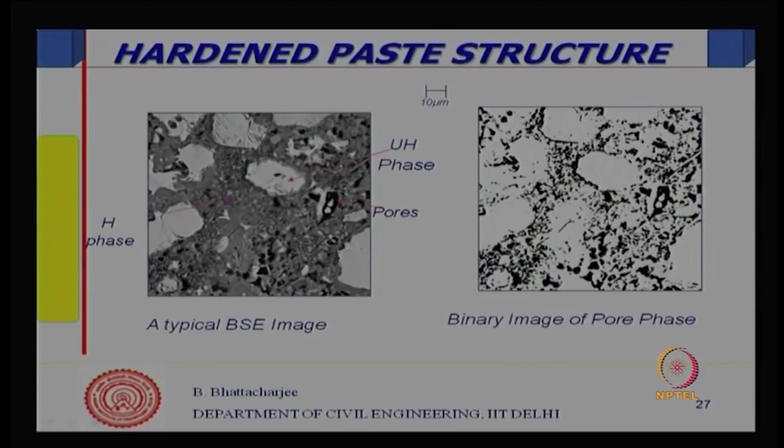In fact, calcium hydroxide is also largely white, and the gray color is the hydrated phase, that is your hydration product. Calcium hydroxide of course remains as precipitate surrounding the aggregate, or it will remain as non-sealing precipitate. So, backscattered electron microscopy confirms the process that I was talking about. In fact, the hydration model that I showed has been developed based on these ideas of electron microscopy and backscattered electron microscopy.